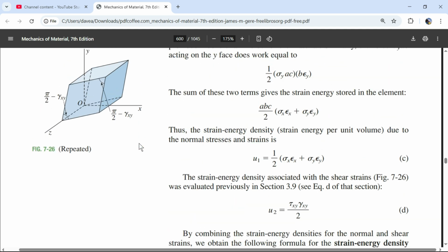Oh, yeah. Shear is going to change distances. It's going to be a force times a distance, a force acting over a distance. Oh, okay, I can buy that. Let's say here's your face, and here's your stress, and that means we have a force in this direction. That force used to be just down here, and then we moved up this length. So this height, if this is a small angle, is just this length times this quantity, shear.